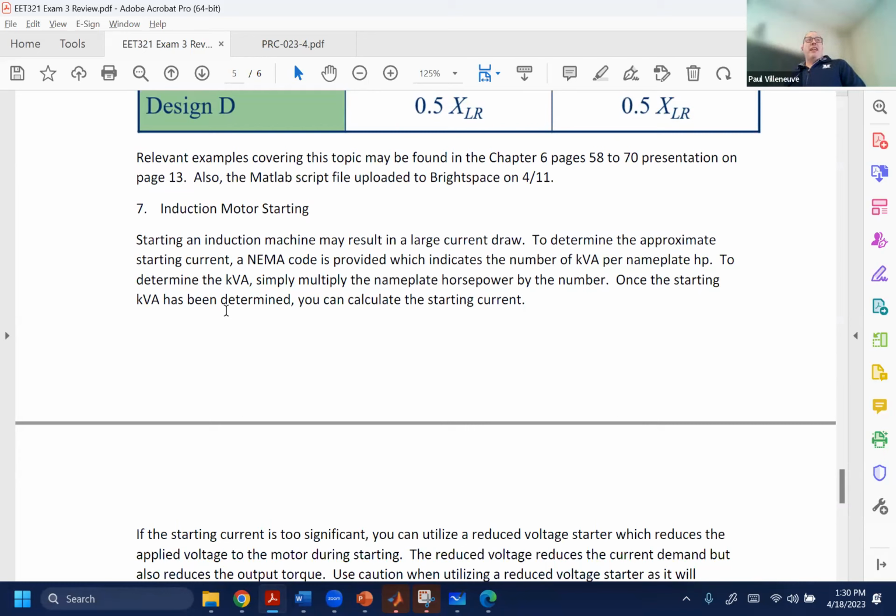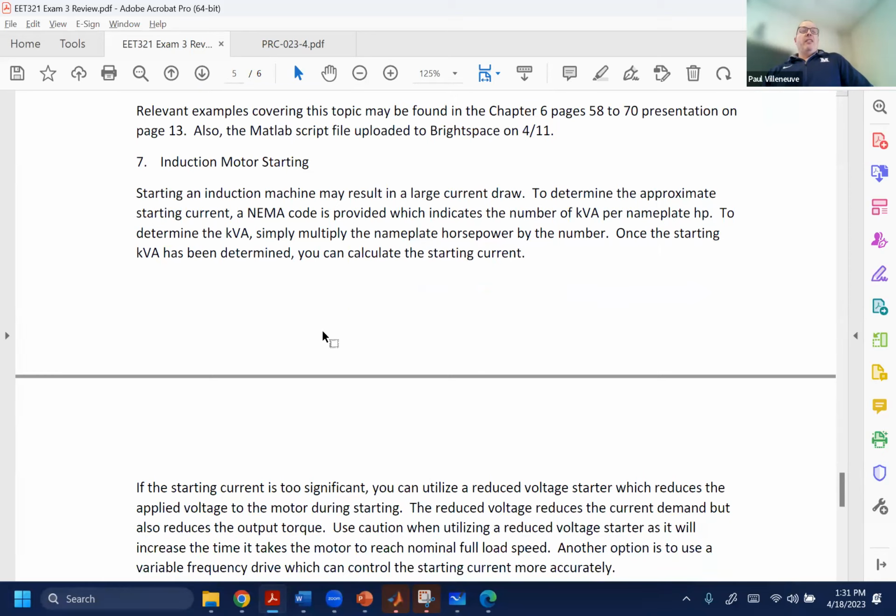And if you have a contactor that's being powered from the incoming voltage, that contactor could drop out. The general rule of thumb is that if the voltage is less than 90%, your contactor will drop out and then your motor no longer is allowed to start. You're going to go back and hit the start button. So at that point, you would have to go in and figure out how to get the thing to start.